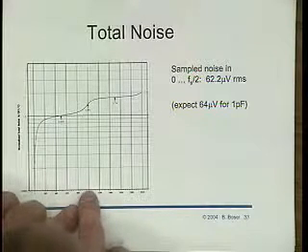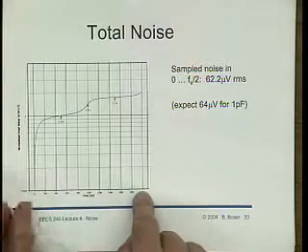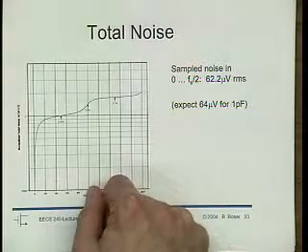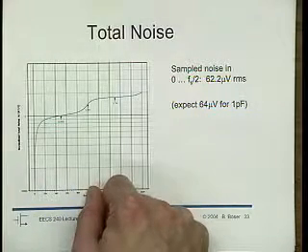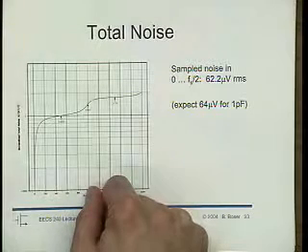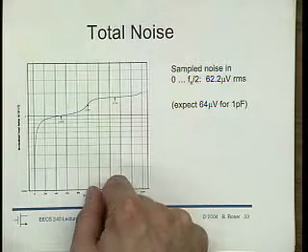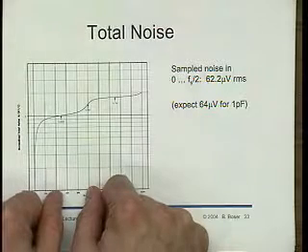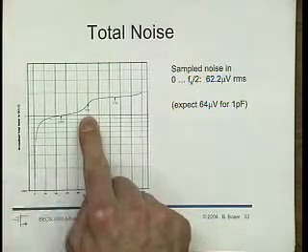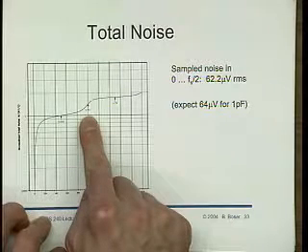And then SPICE is even good enough that if I double the integration interval, then of course the noise power doubles, but then I take the square root to get into the microvolt RMS scale, so I get a square root of 2 increase, and this is a way to calculate some approximation of the value of square root of 2.